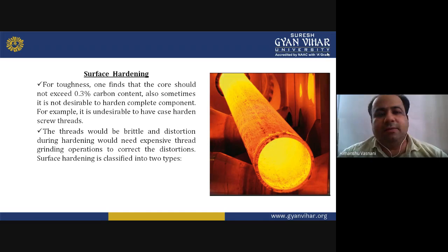Also, sometimes it is not desirable to harden the complete component. For example, it is undesirable to have case hardening through the screw threads, so we don't require them. The threads would be brittle, and distortion during hardening would need expensive thread grinding operations to correct the distortions.